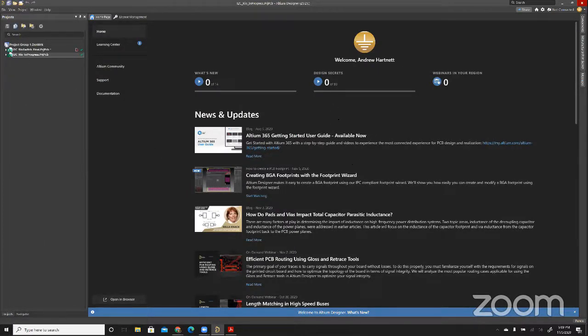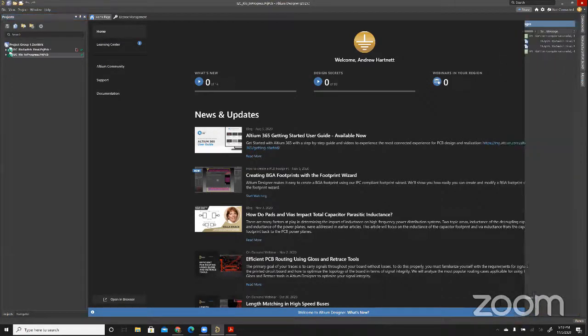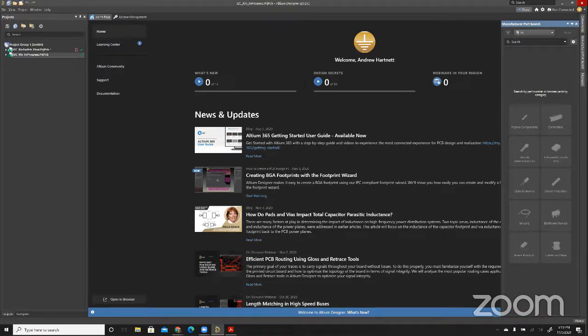There's a big U around Altium that has a bunch of things that you want to be mindful of, unfortunately, on all sides. The left side oftentimes is where, at least by default, the projects show up, and there's a navigator over here, and new panels will open up over here as you do things. This will change depending on what you're doing, and sometimes you'll have to physically change it. Same thing on the right. Typically, there are some things that get docked to the side that you can load up. For instance, right now I've got messages and manufacturer part search docked to the side that I can load up.